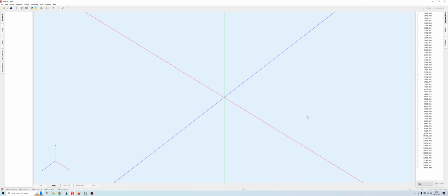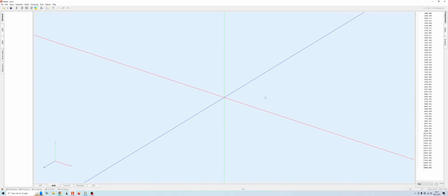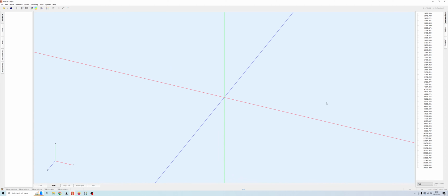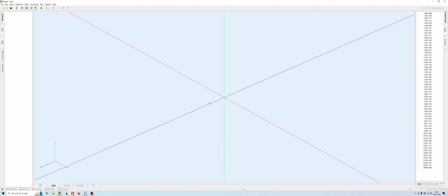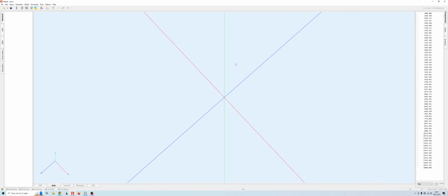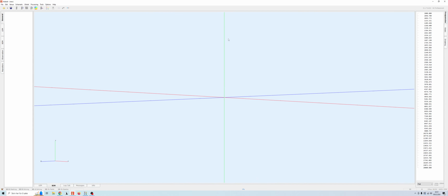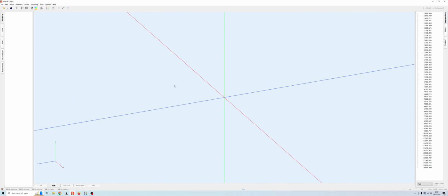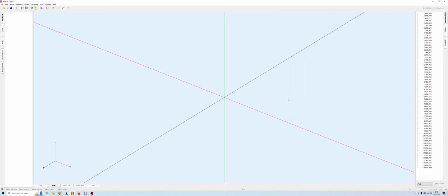I am going to show you how to use the 2D simulation in AKABAK to simulate the mode distribution in a room and the frequency response at specific points in the room. First and foremost, I'm going to show you the 2D mode, because the 3D mode is much less computationally efficient. So if you can get away with a 2D simulation and it is useful, then it is definitely preferable to a 3D simulation.